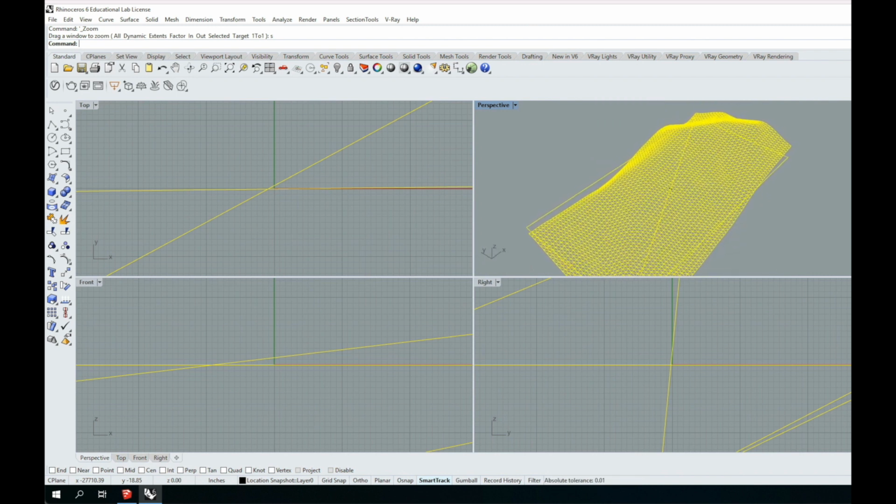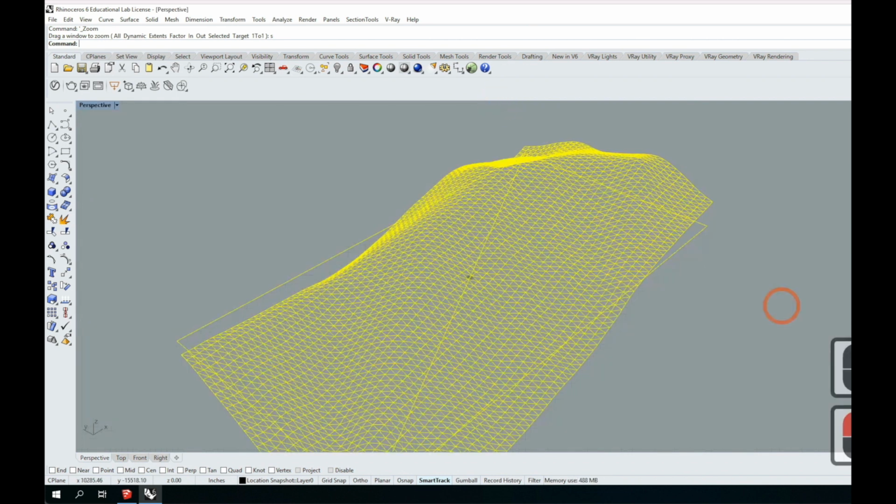That's good. Let's go ahead and make my perspective view large here. There we go. And we'll come over and we'll adjust the layer properties a bit. So I'll click on the Layers tab. You notice that by default, I have a default layer, layers 1 through 5, and then I have some SketchUp specific layers right here. I'm going to go ahead and rename these SketchUp layers. So instead of Location Snapshot, we're going to change that to be called SketchUp.